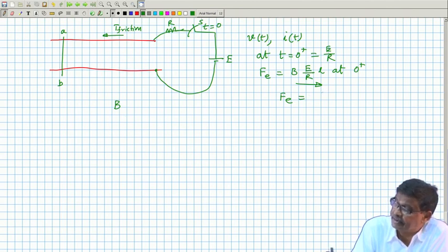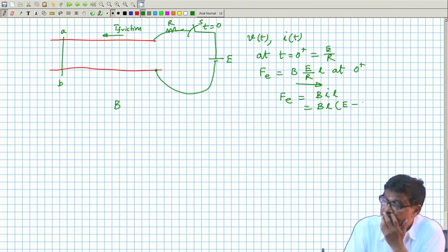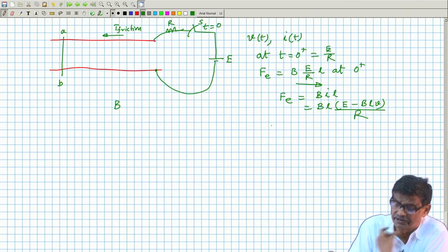Fe at any time t will be B I L, as we have seen, and I at any time t is E minus B L V by R. I am just writing very fast.